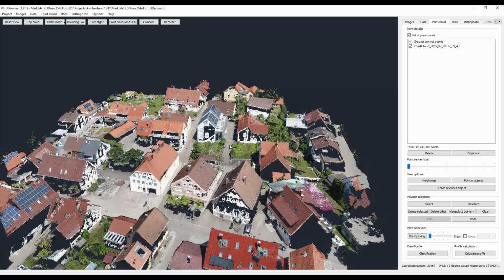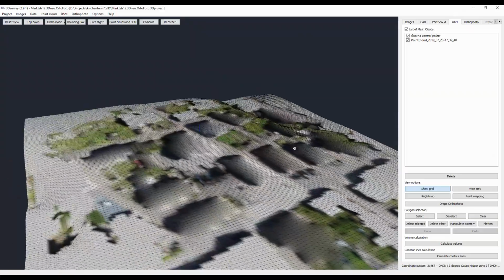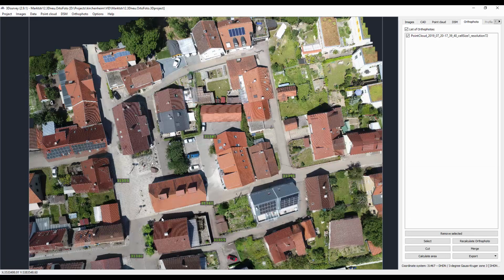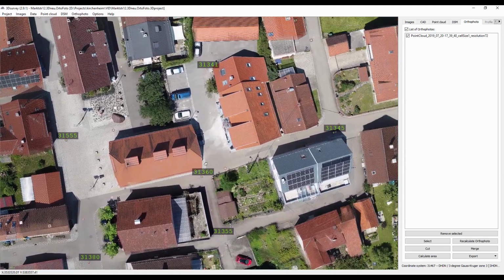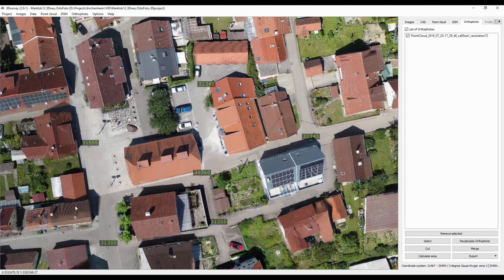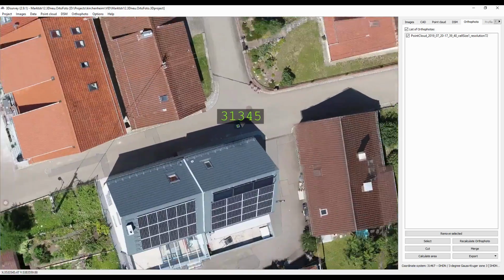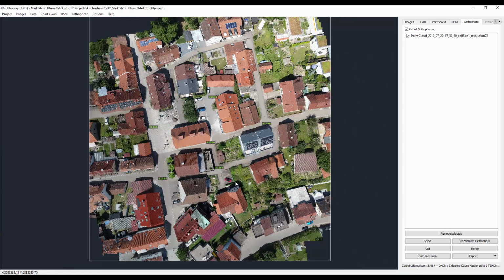So from this point cloud, we then created the digital terrain model for our area of interest. And lastly, the result that we were looking for, our orthophoto map for this area. So you will notice that we had a pretty small area of interest, so we signalized only 6 ground control points in this area. So this was now the first example.